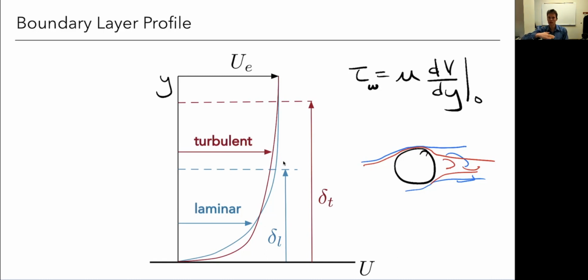If we're at a very modest angle of attack, we could have laminar flow quite extensively, but we won't be very robust. As we increase angle of attack and we need to navigate a more adverse pressure gradient, we would like to have turbulent flow at this point so that we can navigate that pressure gradient without separating, so that we can maintain higher angles of attack. So that's why we don't actually want 100% laminar flow. We do want a decent amount, but not to go too extreme.